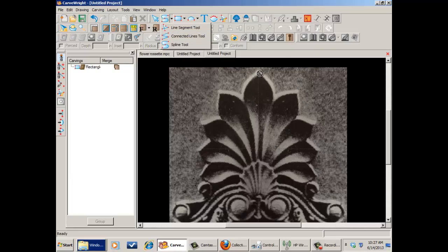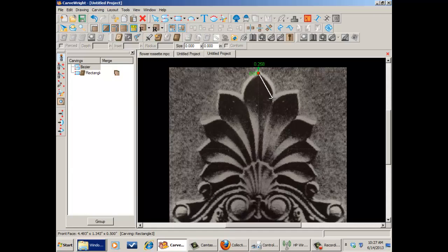The Smart Spline tool allows you to make those changes without having to change the tool. So I can put a point down here, and I can pull out a curve. I put that next point down, and then with the mouse still held, I pulled down, and it pulls out these control points, which allow me to define that curve however I want. I can just position it, and then it's still connected there, so I can continue on.